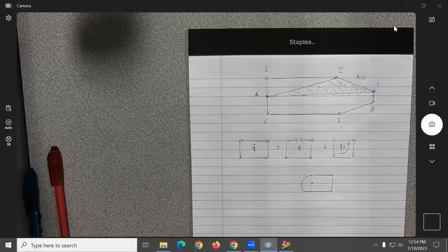Again, for the people that did it with Radosta, I'm not saying one is better or easier, but did you understand that basically we are doing the same thing? What happened is that Radosta did it at the end of the semester, and he used the principle of virtual work, which I don't think is necessary. You don't need it. Basically, what you need is an additional equation. That additional equation we are using is that the angle of twist on the cell needs to be equal.